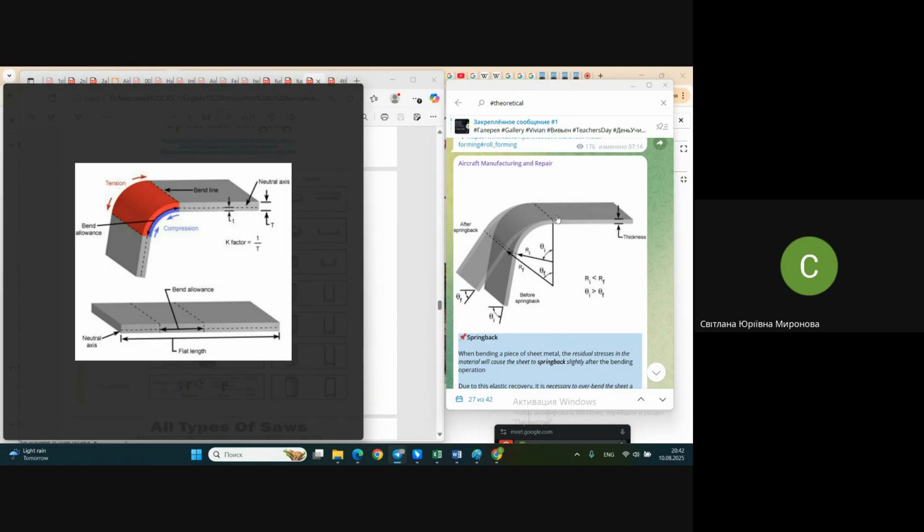But if you're trying to bend something a little bit with big radii, spring back effect is significant, and moreover it's very notable on this big radii, because really you're trying to change the shape not much, and this not much is even spoiled significantly after. And some ways, some technical means during bending, are directed exactly to release, to compensate the spring back effect above all.